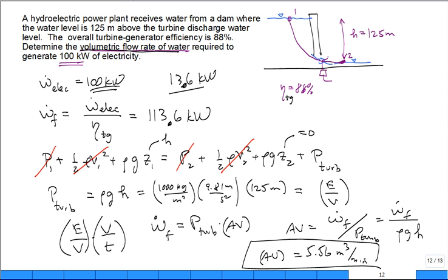If you assume that 13.6 kilowatts of mechanical energy is dissipated into internal energy due to friction in that turbine, resulting in an increase in the temperature of the water, you can calculate the temperature increase, assuming a specific heat of 4.18 kilojoules per kilogram Kelvin, and you'll find that it's a whopping 0.035 degrees C. Are you going to be able to measure that? Not on a good day even. So it's easily dissipated by making the water an itty bitty amount warmer.